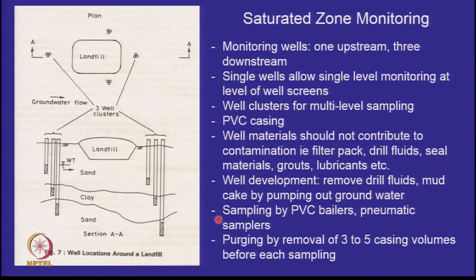To pick up the groundwater samples, we would like to use PVC balers or PVC pneumatic samplers. And in any case, whenever we want to sample at a particular location, suppose I pick up a sample today, and then I want to come back after a month and pick up a sample, I don't just send my sampler to this level.